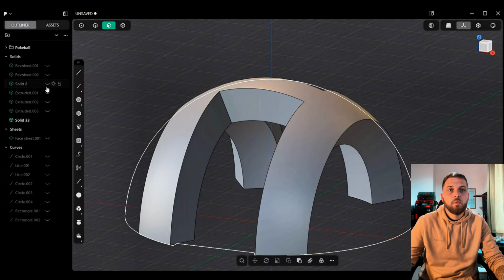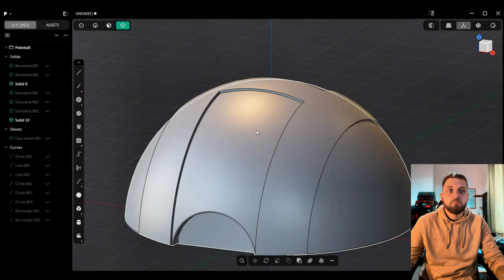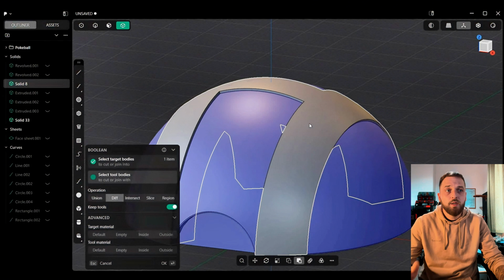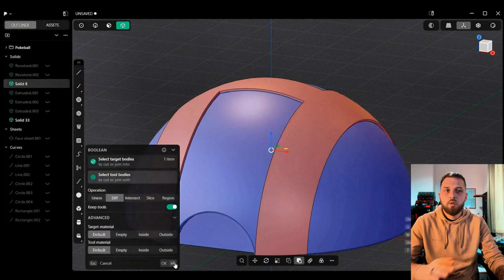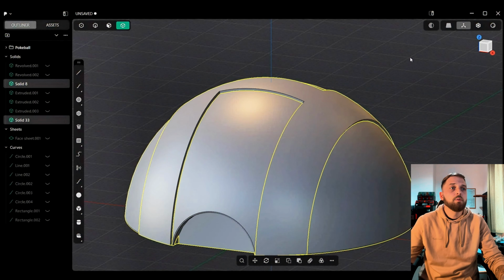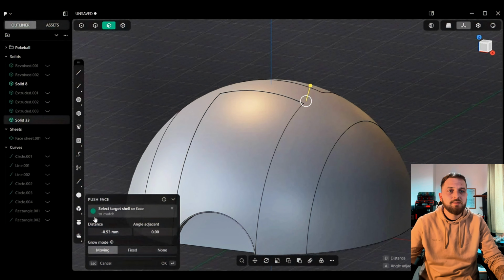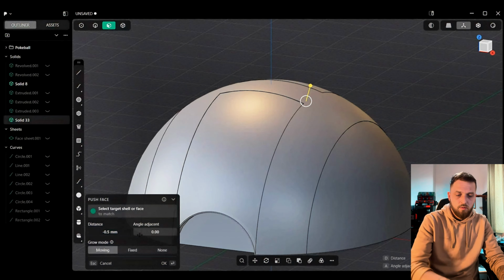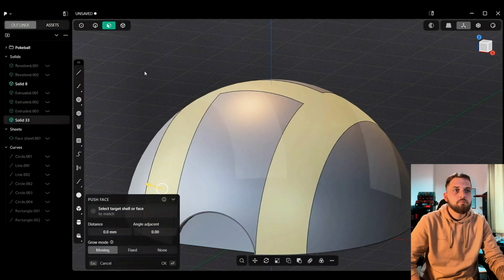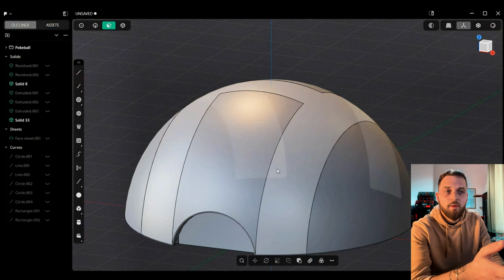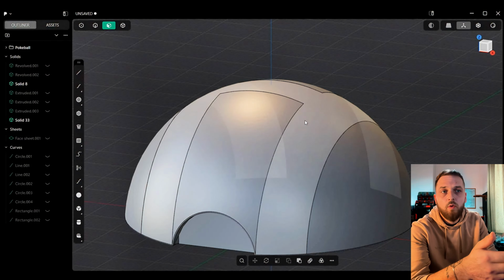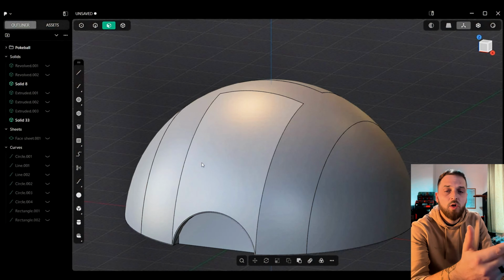There you go. Bring this back again. Solid selection. Q. And then remove that part. But you want to keep the actual removal tools or key tools. There we go. Now bring this back in. 0.58. There. Enter. There we go. Now, same again with this. You want to go around all the edges, bring it in by 0.1 millimeters so everything connects together properly.